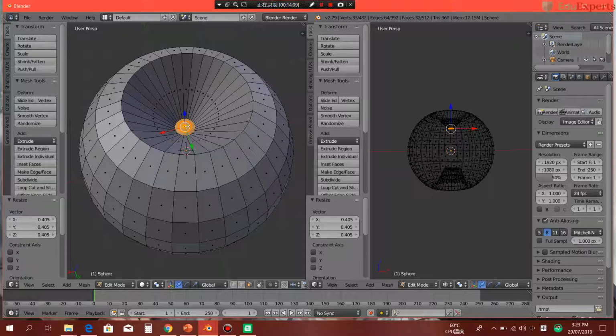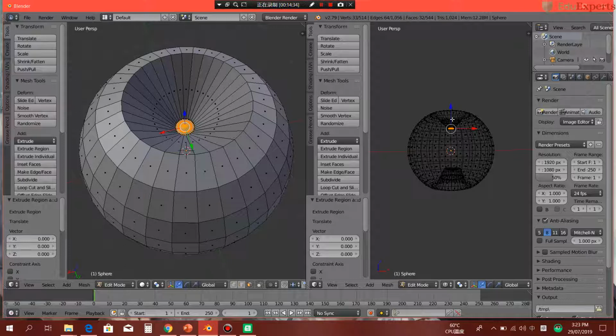Okay. And now what I need to do is press the E button. Actually, you can do this in right side window in the structure view. It will work much better. So if you press E button, E for extension. In this case, you are not actually dragging this part, because if you drag it, for example, I just show you, if you press G button for drag, okay?